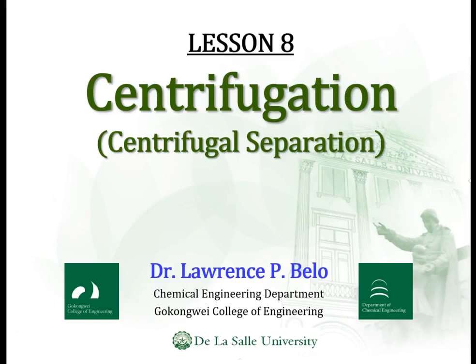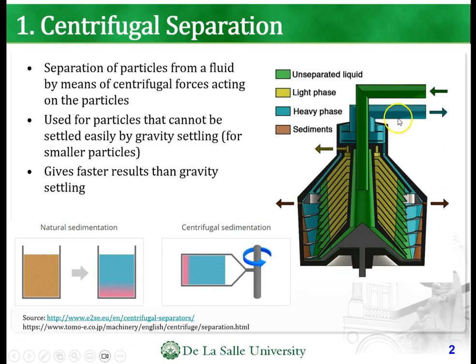Okay, so for this module, we'll have centrifugation, or centrifugal separation. First, let's look at the figure of what centrifugation is, and let's look at the definition. It basically deals with the separation of particles from a fluid by means of centrifugal forces acting on the particles. They're used for particles that cannot be settled easily by gravity settling.